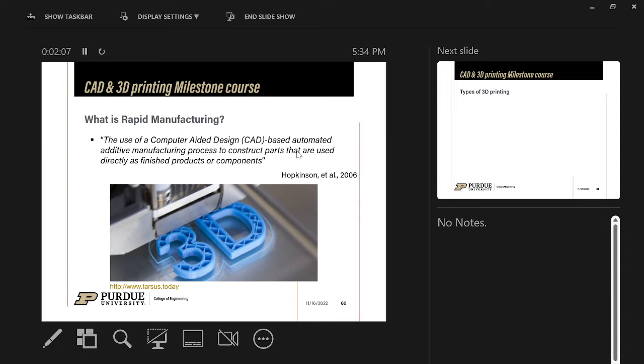Without 3D printing, you have to do something called drawings. It's a big part of Fusion. We're not going to cover it in this class. It is really cool, though. I think we have some other classes here that might go a little bit more into it. But other ways of manufacturing, right? If you're going to take a part that you made to a machine shop, you can't just give them a CAD file because they're not going to take it. You need a working drawing. So that takes a lot of time because you have to get the layout correctly. You have to get callouts. So you have to tell what every dimension is, and just like that. And 3D printing really just cuts it in half because you can just download the file, convert it over to a different type, and within minutes you have a print starting.